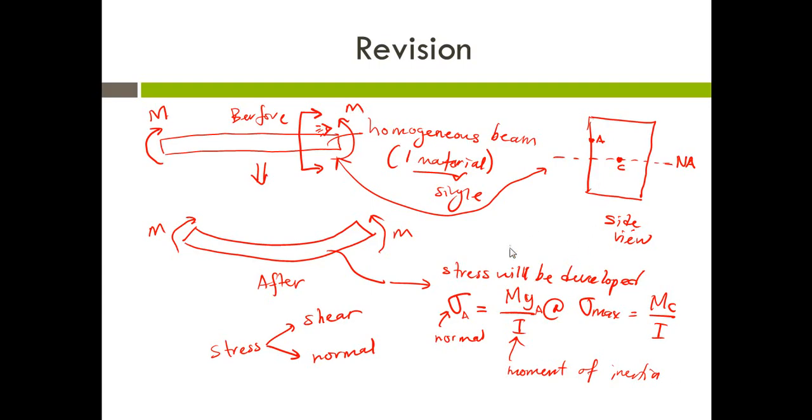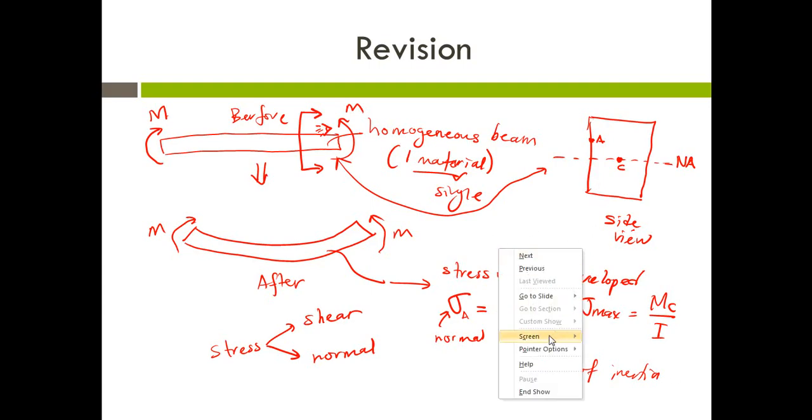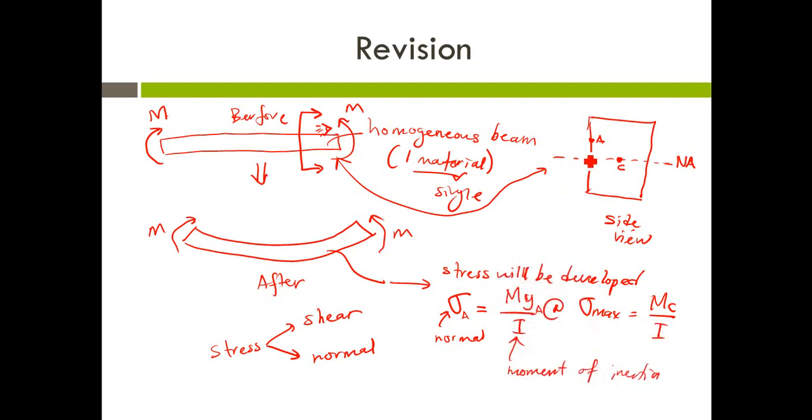So what is the y_A? y_A is measured from the neutral axis to the point A. So that is the y_A. Let's say the question asks you to calculate the stress at point B, for example. That will be the y_B.